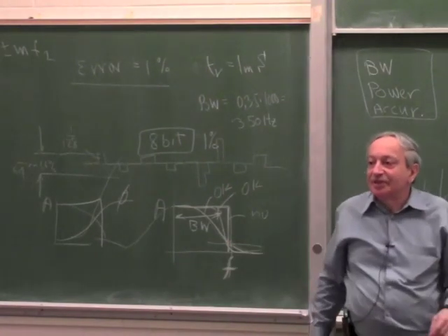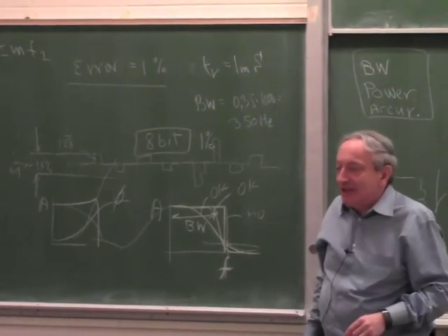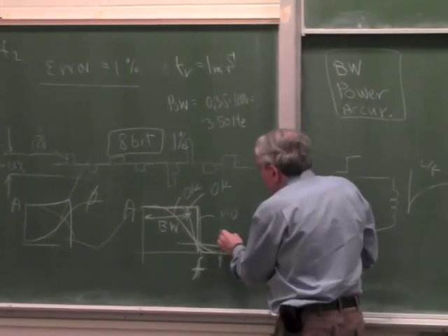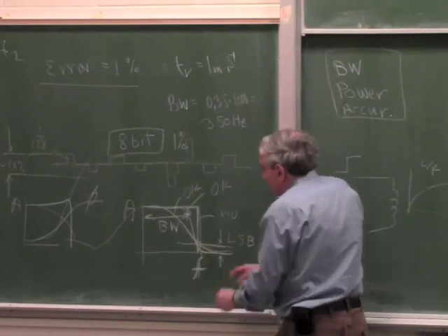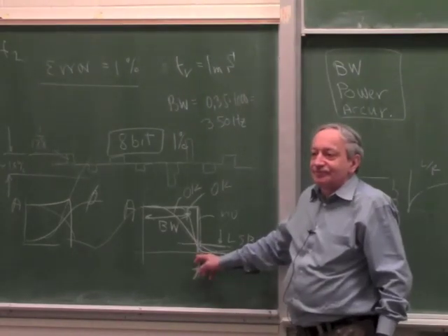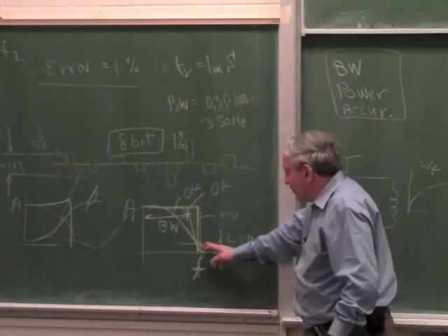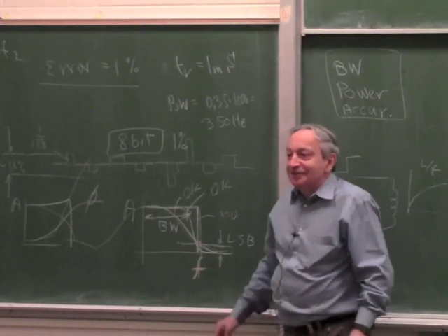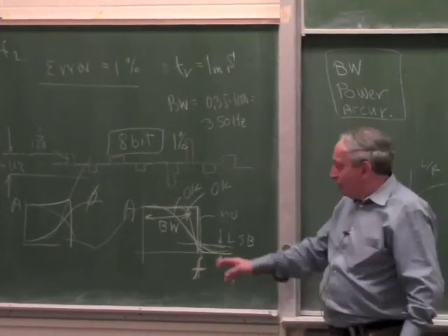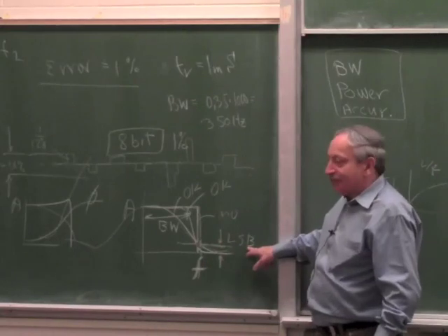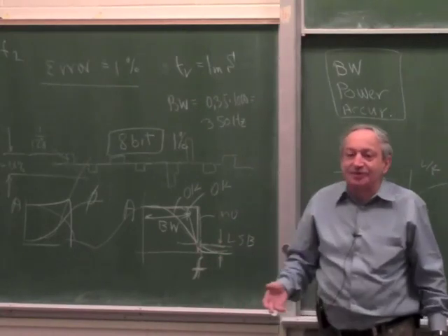The accuracy of the least significant bit. And this has to be less than the least significant bit, but at what frequency? Because every filter eventually will go down to a least significant bit, but the question is where? So the two coordinates of this important point, it has to be less than a least significant bit at what frequency?